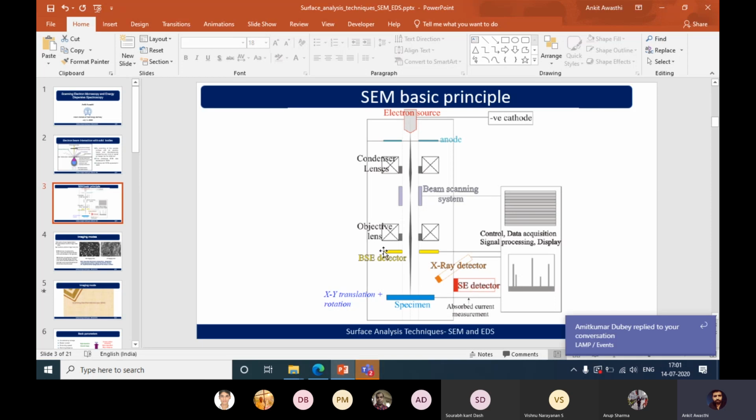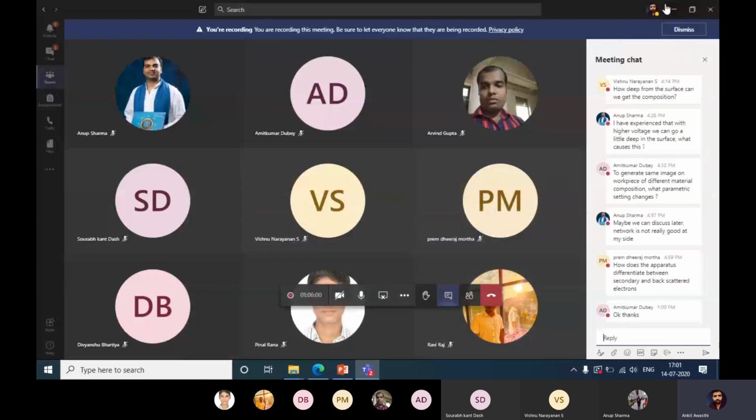It is not like the apparatus is different. All SEMs have these modes of operation, whether backscattering mode or secondary electron mode. If you want backscattered mode, you have to tell the operator beforehand that you want backscattered imaging mode on for your morphology analysis. That's the only difference, and all the equipment has the same apparatus for performing these two analyses.